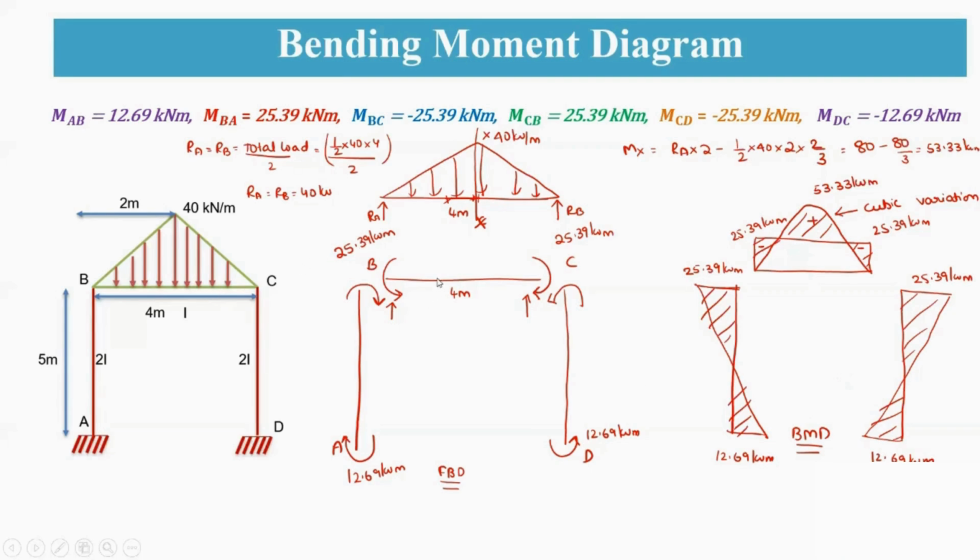So what I have done is, we first draw the free body diagram. After drawing a free body diagram of the external moments that we got, the final end moments, I have drawn the bending moment diagram. But there is an external loading on BC. So I just consider that beam to be a simply supported beam, and I found the reactions RA and RB. After getting the reactions, I calculated the moment at this point. Why? Because moment at A will be 0, moment at B will be equal to 0. I just calculated the maximum moment at the center. Why? Because it is a symmetric loading. So I just got the moment to be like this. You can just see the reaction, and this is how we got the moment. So this is a bending moment diagram.